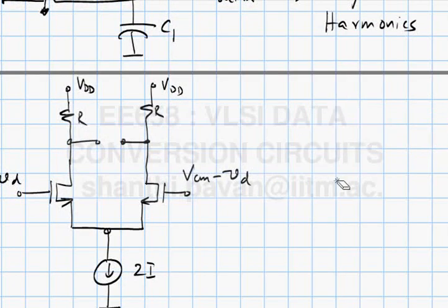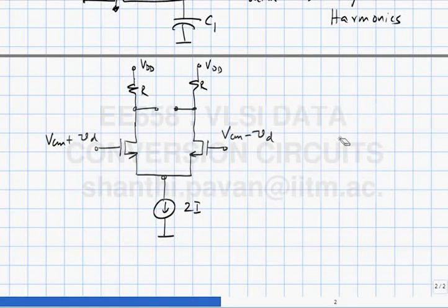If I wanted to build a fully differential op amp, what do you think the governing relationships must be? So in a single-ended op amp, the absolute output voltage is a large multiple of the difference between the two inputs. In a differential op amp, the differential output must be a large multiple of the differential input.